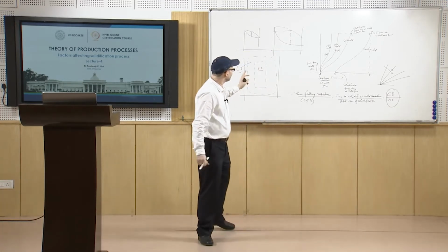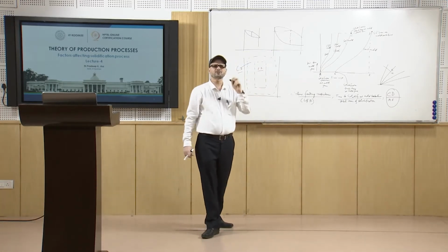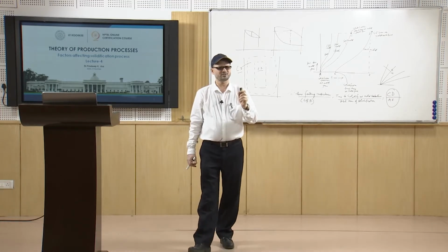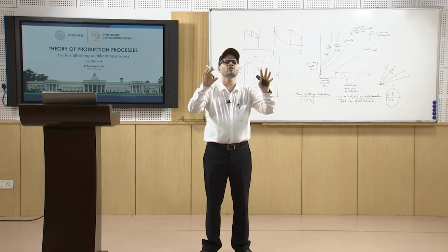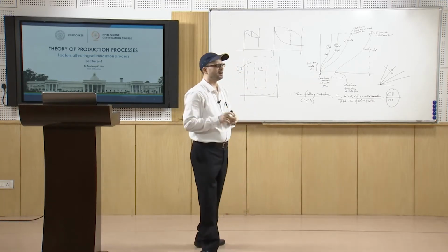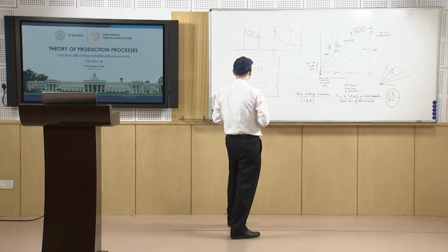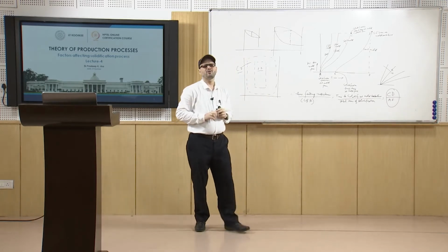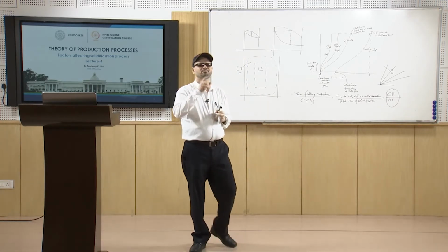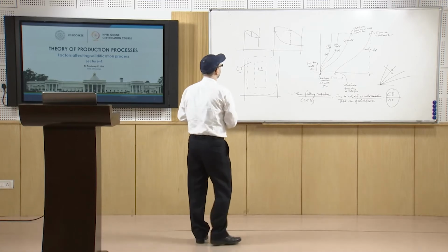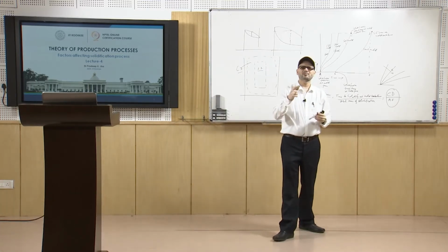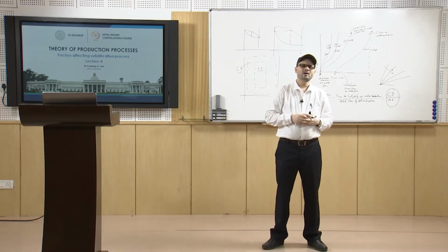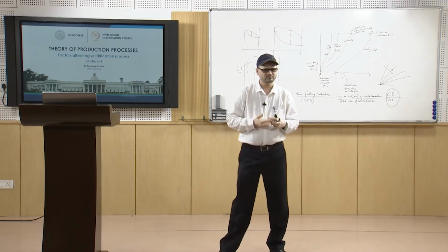So, there is another practice which is followed in industries, where you promote the formation of more nuclei. One of the methods to promote the formation of these equiaxed grains, or to have more nucleation sites, is with the use of inoculating agents.